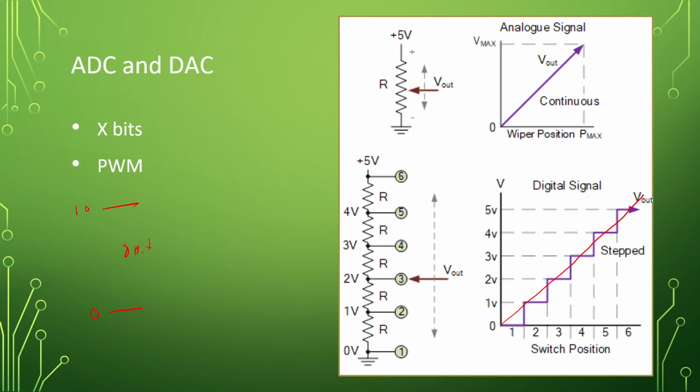Now, if we went up to, say, a 10-bit, which would be 1024, you would now be able to go down to about 1/4 of a degree of change. So you've just changed how many steps, right? You went from having this many steps in this picture. Let me go ahead and clear my ink. You went from having this many steps to now doing this. You just quadrupled the number of steps by going from an 8-bit to a 10-bit.